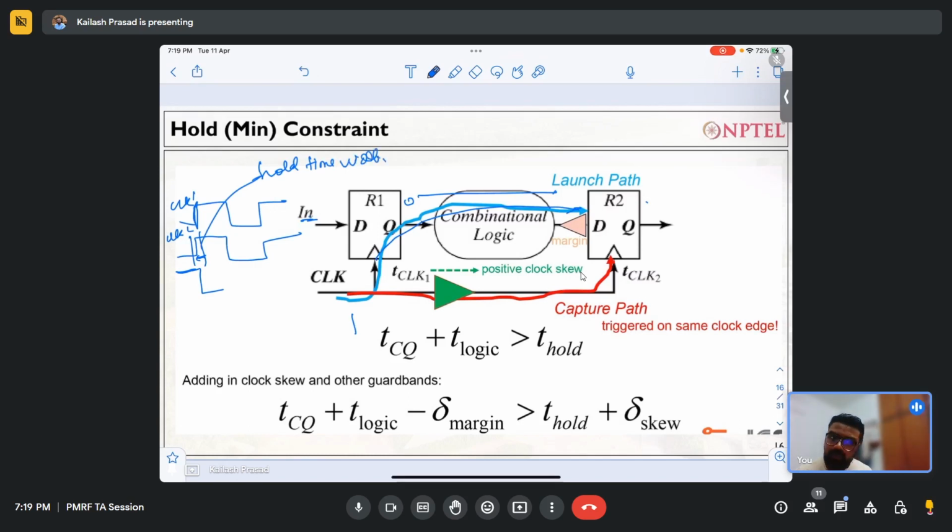right? So whenever you are calculating hold time or checking for the hold time violation, you are actually looking into the first clock edge of the second flip flop itself. Because as soon as this clock comes, data has moved very fast to this particular flip flop, and the next flip flop actually requires the data to be held for some time, but data has changed in between.